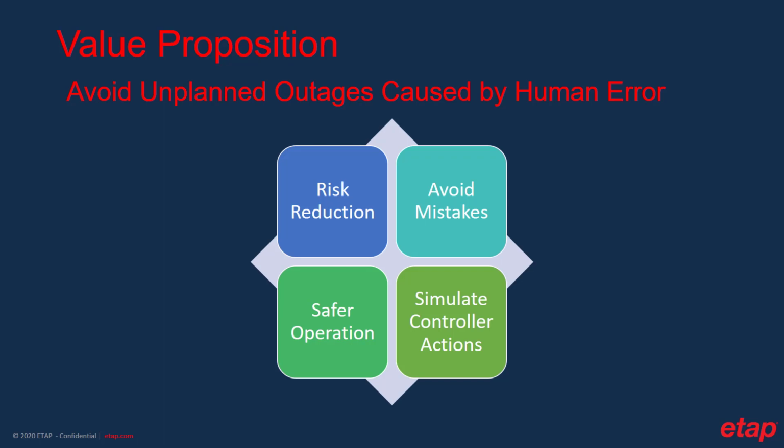It ties together transient stability simulation with emulated automatic controls, including relay characteristics, interlocks, exciter, AVR, and speed governor, generator capability, etc. The high-fidelity digital twin provides trainees the ability to learn how to react correctly when a similar situation occurs in the actual plant, resulting in fewer equipment stresses and the ability to correct procedure errors.